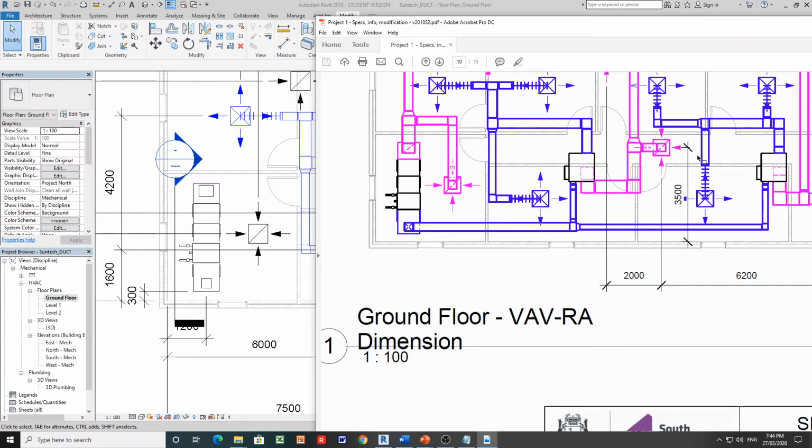So the VAV box now is part and parcel of a component. Now all this coil over here in this AHU is a dummy except for the fan unit. The fan unit is for the supply air system. Later on, for the return air system, we have a mixer. The rest are just dummy. Okay, so for the supply air system, it will contain the 2 VAV boxes and also a fan unit.